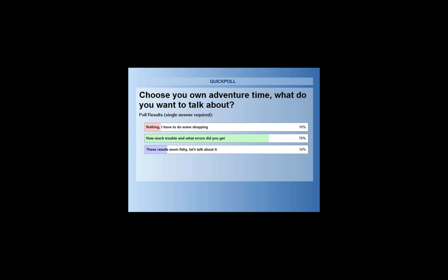I can't think of a good example right now, but it usually has more to do with a mixed convection approach, where the flow rates are much higher, or you have a fan somewhere in there that's causing a little bit more turbulence. So you might extend those upside down Ts very far away on the bottom side along the tabletop, so that there's more of a disconnect between the inlet and outlet. The problem with that is that the top surface still has a tendency to have an inlet and outlet profile. So it becomes more of a balancing act of how you develop that. Right, how small those are going to be. Yeah, it gets very complicated very quickly.